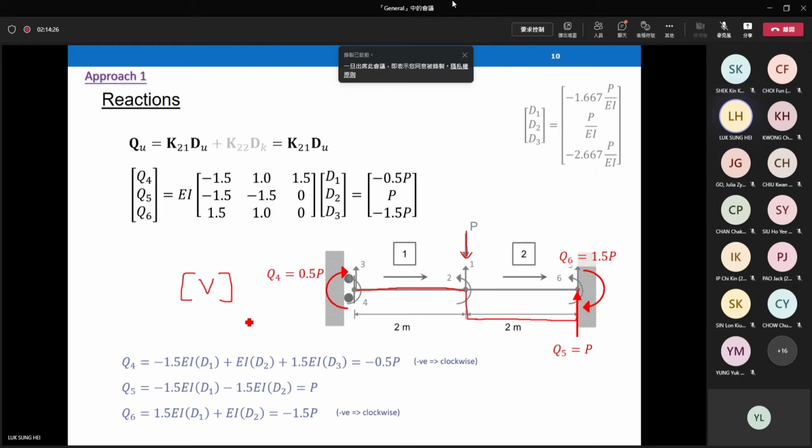Moment diagrams you can also draw using the graphical method. Depends on the side you would like to use. You can draw the moment diagram on the compression side or on the tension side. We have moment on the left-hand side of this structure. And then what about the change right here?